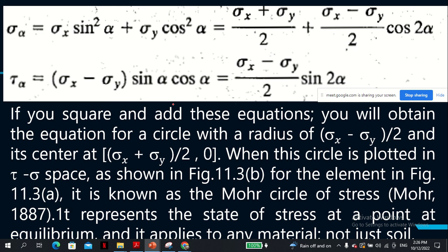And in fact, this is what is defined as the Mohr circle, and this is what we are trying to explain, such that if you draw your Mohr circle here, and you know what is called the pole, from the pole you can measure any angle you want, and from here you can read.